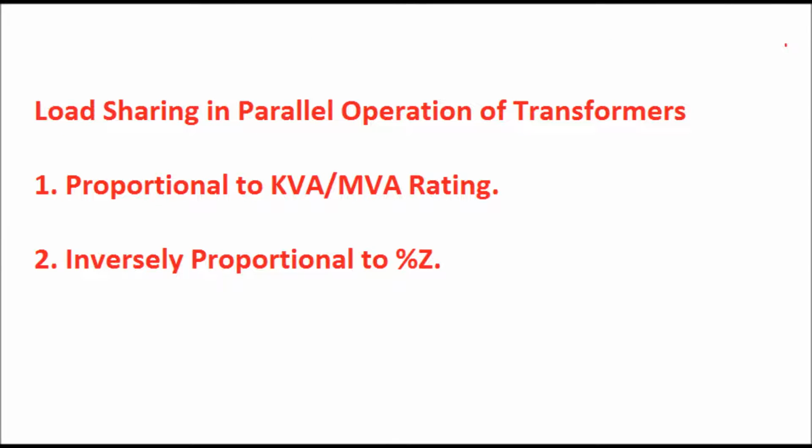Now, how will the load be shared in parallel operation of transformers in a substation? The load will be shared by the transformers in proportion to the kVA or MVA rating of the transformer and inversely proportional to the percentage impedance of the transformer.